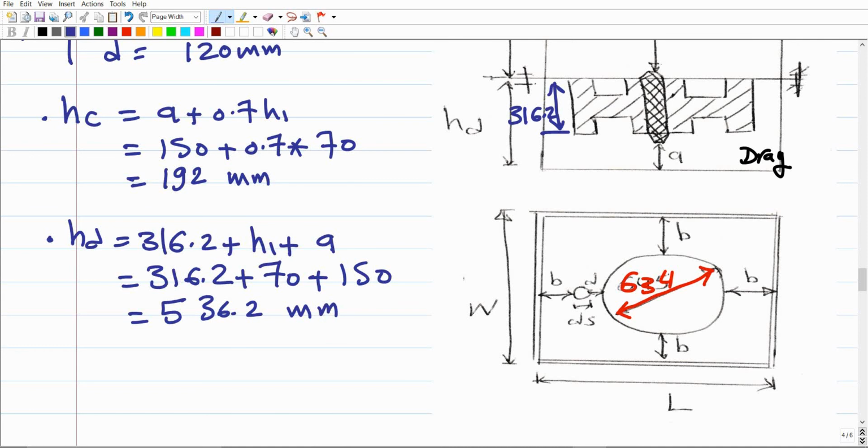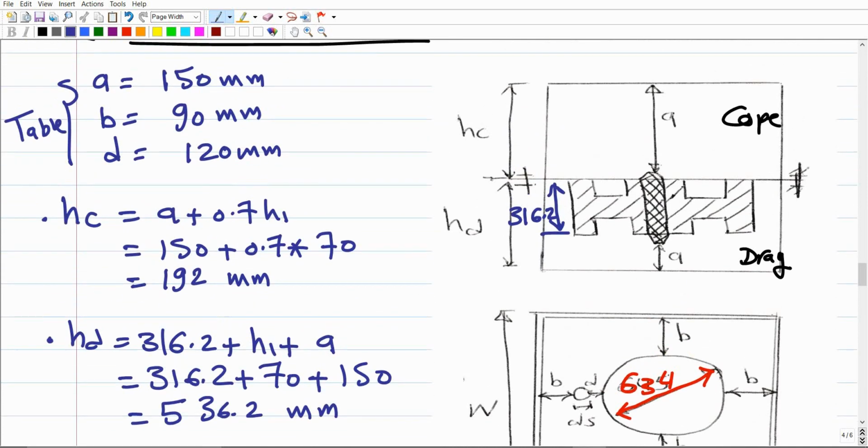So have a look at these two heights. This indicates that we would have to use a flask with two different pieces or parts, in such a way that the cope has a height that is different than the drag. We can proceed with this option, a hybrid flask, where the cope has a height different than the height of the drag.